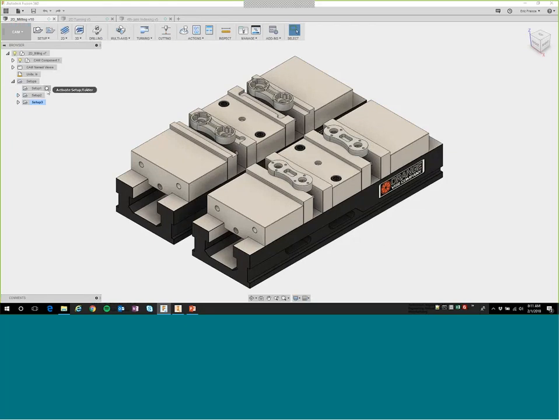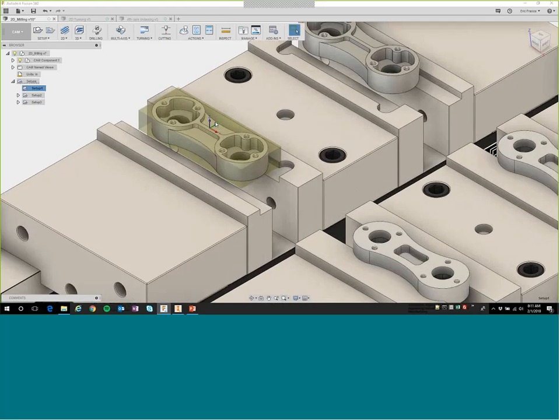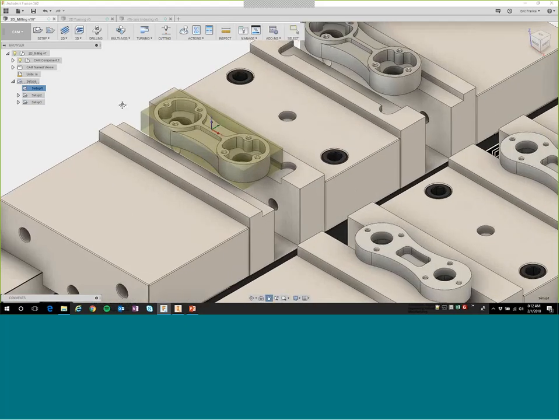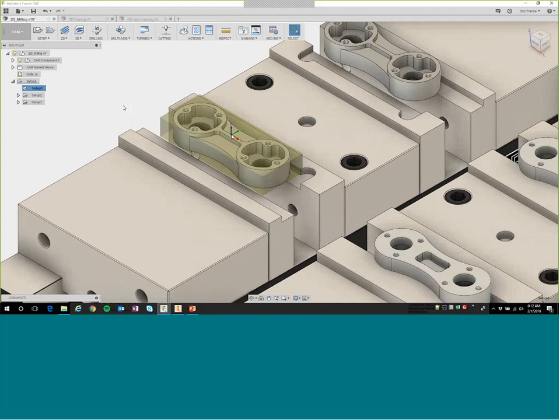It identifies that we have 3 different setups. We've got just an initial one to show that first setup aspect and do a little bit of milling, and then setup 2 is going to finish out the top, and then setup 3 is going to take a look at the bottom and how we would finish off the part completely. If we start out in setup 1, as we step into this, we can see we've got our WCS origin identified there in the middle, which isn't quite where we want it.